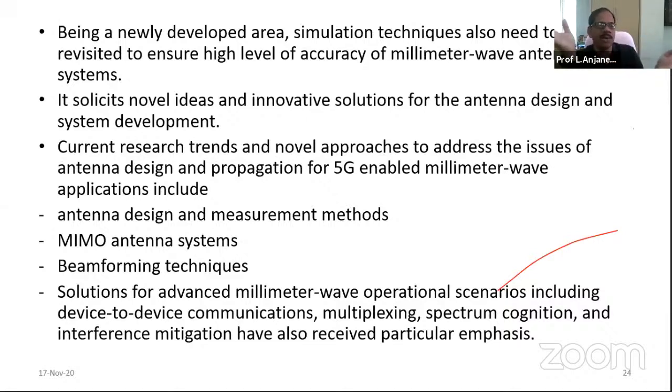We can't even cover that much of the growth that has already taken place, and it has already been developed in the millimeter wave area. Mainly, several new ideas have come to address the issues of antenna design and also propagation, for 5G, fifth generation enabled millimeter wave applications. Some of the approaches are new antenna designs, new measurement methods, and then MIMO